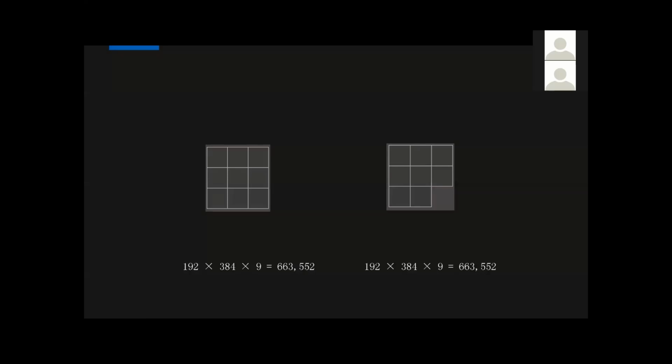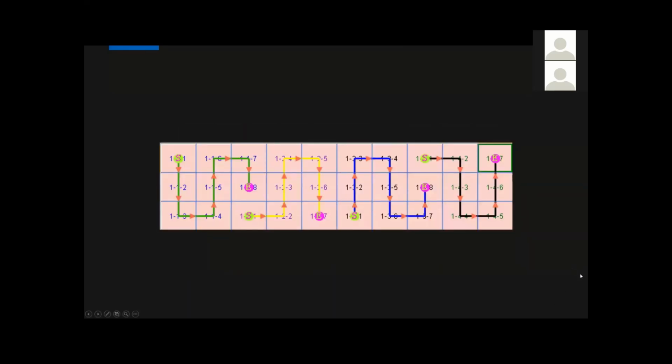So we cannot connect this way. If we connect 8 panels on port 1 like this, it is still calculating the whole 9 panels, which is over the loading capacity. The same goes for port 2, which is still calculating another 9 panels. Even the third row is calculated twice in this system. So now we know why this is not going to work.